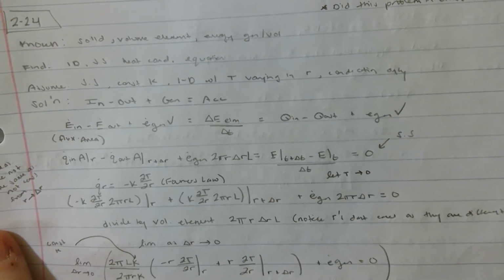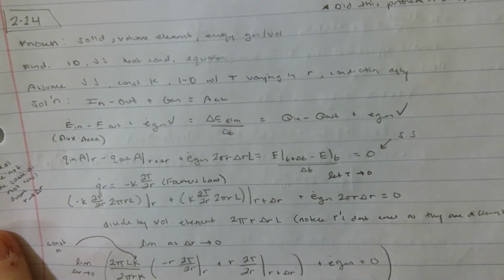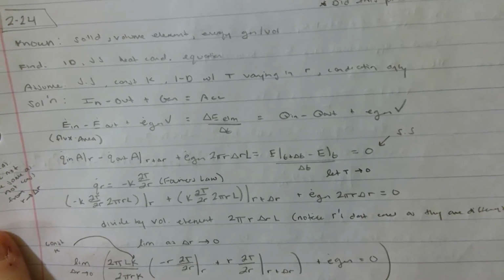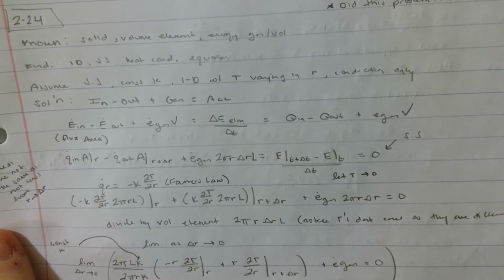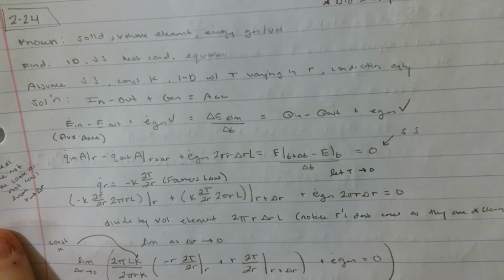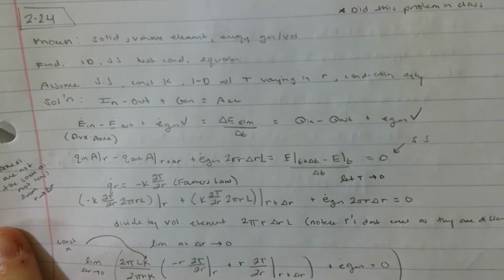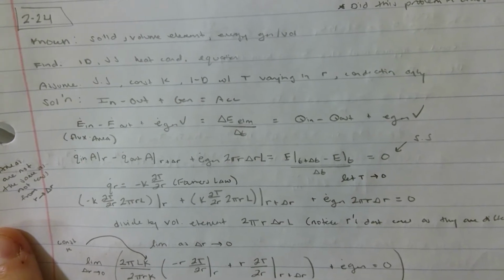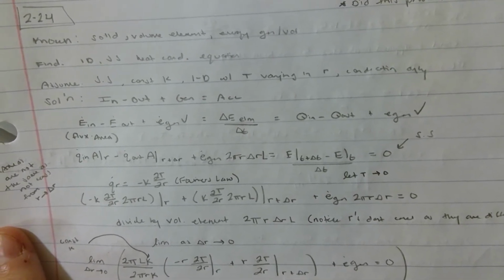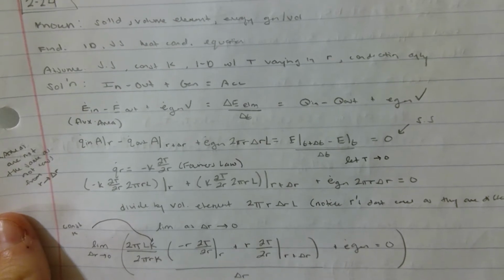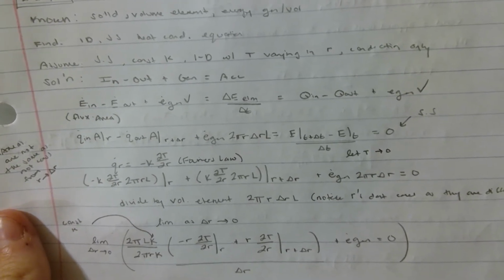So for problem 2-24, we are going to be using the chemical engineering equation of in minus out plus generation equals accumulation. As we can see here, this is the flux times area. In, out, generation is equal to delta E over delta T is equal to Q in minus Q out plus E gen volume. We can then begin to plug in as E in and E out are equal to flux